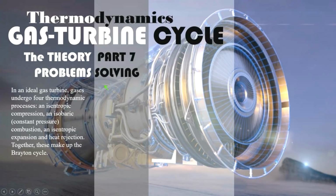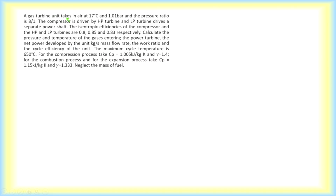Now the second problem solving example, for a two-stage turbine. A gas turbine unit takes in air at 17 degrees C and 1.01 bar and a pressure ratio of 8:1. Please bear in mind, the greater the pressure ratio and the greater the adiabatic index, the higher will be the efficiency of the gas turbine unit.